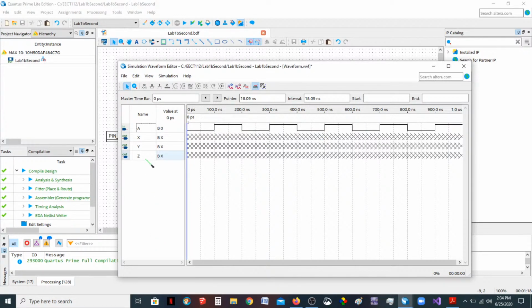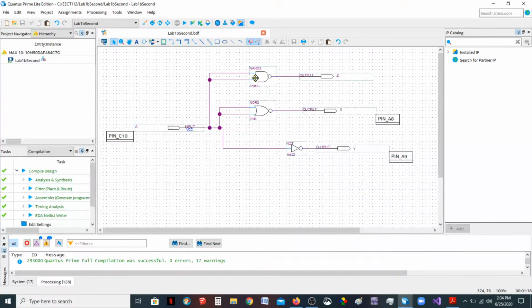All right. So before I do this, I'm going to come back to my BDF here. If you have 0 and 0, that gives you a 0. Invert it, that gives you a 1. If you have 1 and 1, that gives you a 1. Invert it, it gets you a 0. So what I'm pointing out here is this should accomplish what the other 2 things are accomplishing. These 3 should be identical to one another.